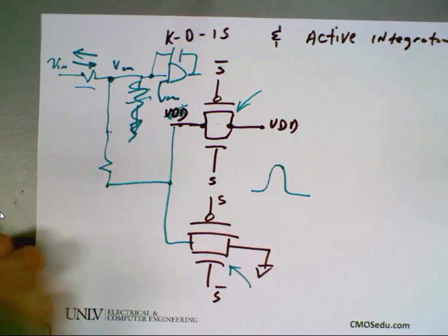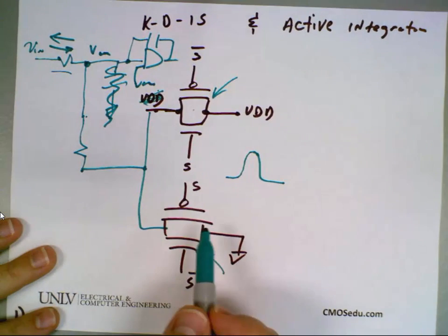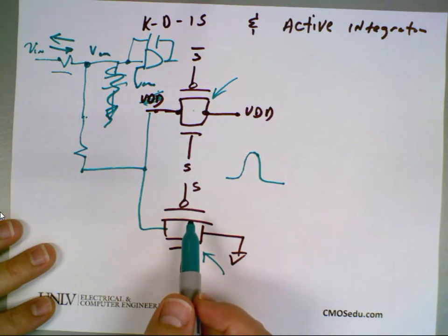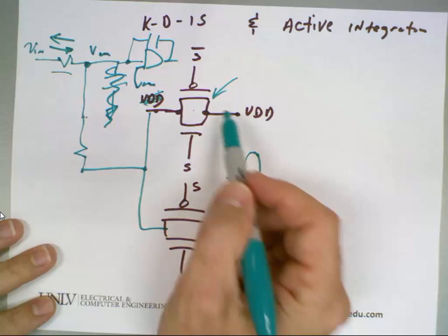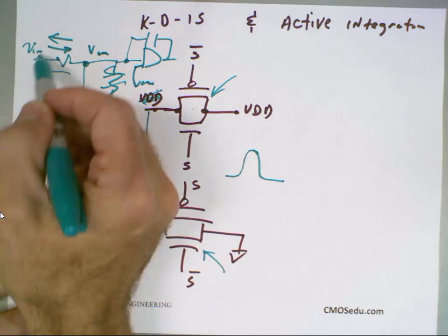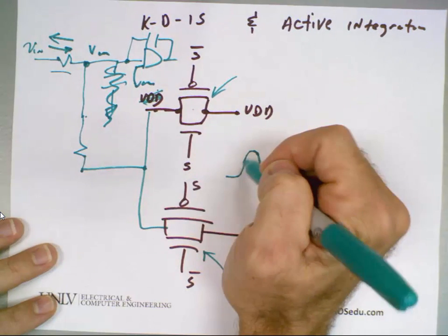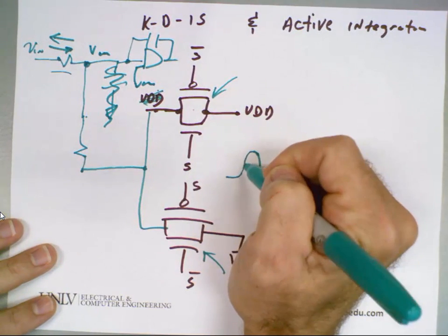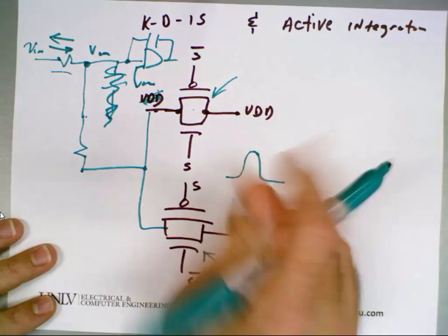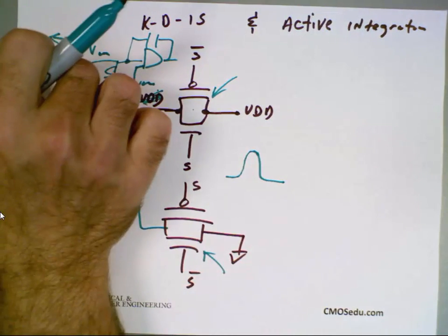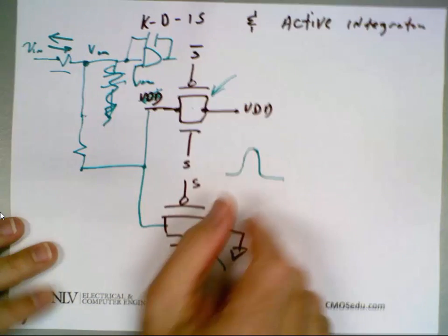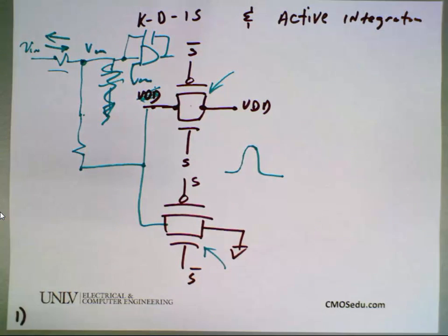Now there are a lot of issues here. One is you're not necessarily going to have a one-to-one correspondence between the digital signal you read out and your analog input, because the analog part is going to be exactly equal to here, but the levels and the correspondence, I think there'll be some offset. But you don't care. You don't care if it's got a gain problem, because gain issues are trivial to fix digitally. You care about whether it's reproducing the input signal correctly, okay?